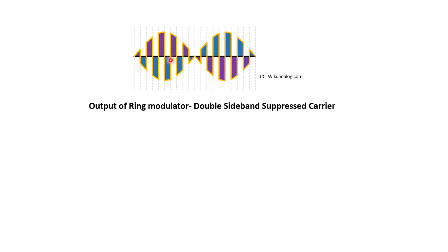If we combine these two waves, we get the entire waveform of the output voltage, which is obtained when the modulating signal as well as the carrier signal are simultaneously applied to the ring modulator or the chopper modulator.